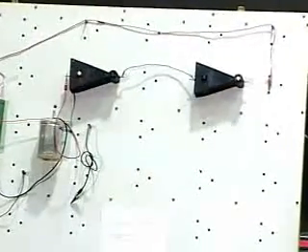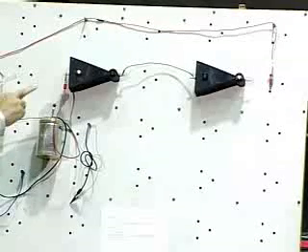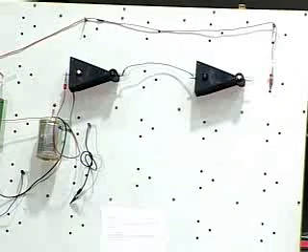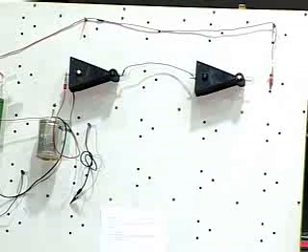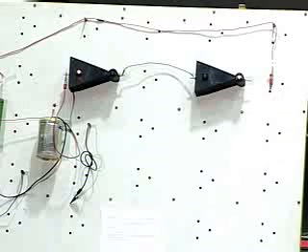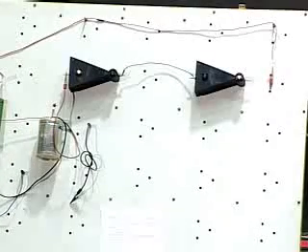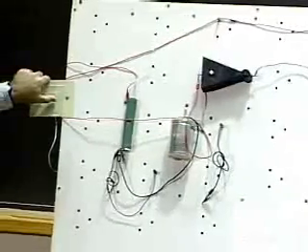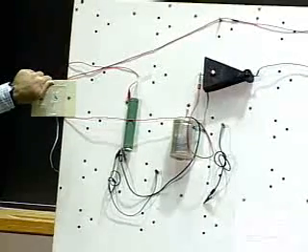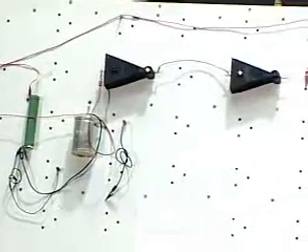Okay. And now I'm going to take the input out. As you can see, it's stored. In fact, we have to wait for a very long time. We don't have enough time to wait for this to discharge. So instead, what I'm going to do now is add also the resistor. Okay? So now I'm going to flip the resistor in parallel with the capacitor to imitate what happens when we have an input resistance.